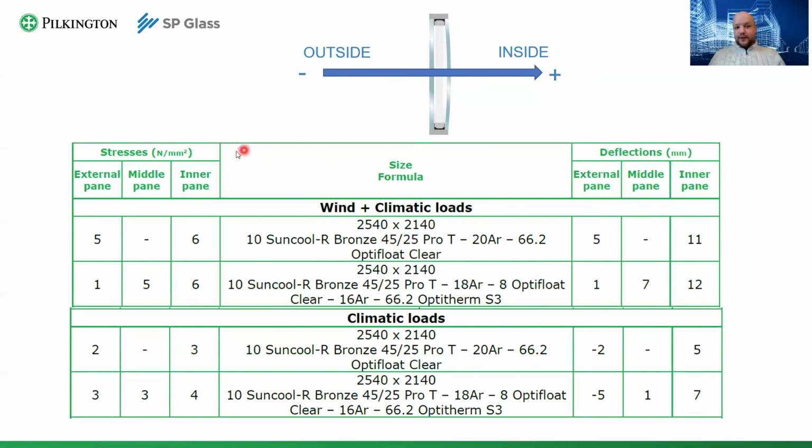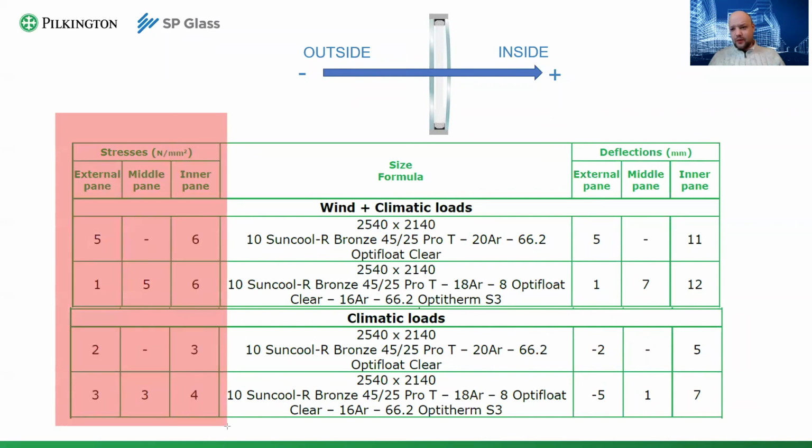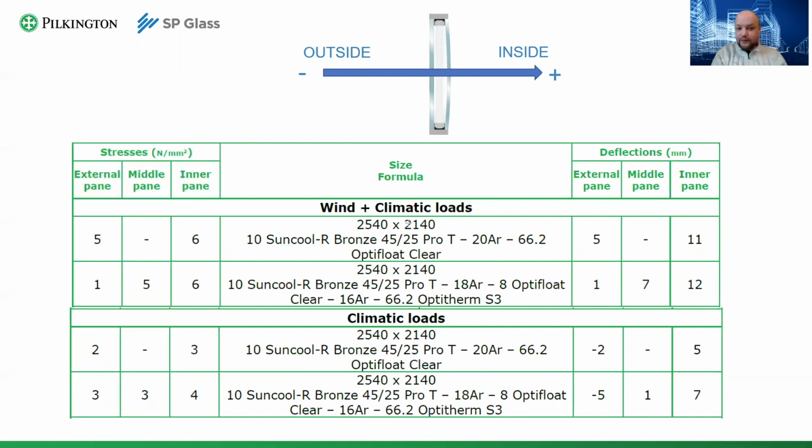So if in the left part there are stress calculations, all of the stress here is very low. This is the case of the cottage in the Mediterranean area, so not exactly a strong wind for a cottage. Loads are, even for the worst part, any type of glass will do. But take a look at the deflections.